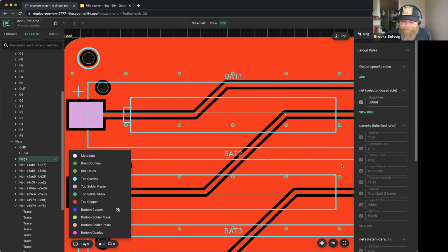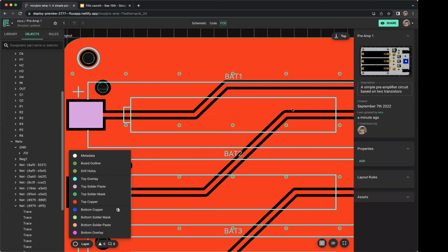Okay, Andrew, one more time. It's the ground via spacing. That's what I was talking about. The automatic vias that are placed. I was just wondering if you're going to have the ability to set, for the ground vias that fill in the ground fill, that spacing. Is that like having different zones where there would be different spacing? Is that sort of what you have in mind? Exactly. Different zones would have different densities.